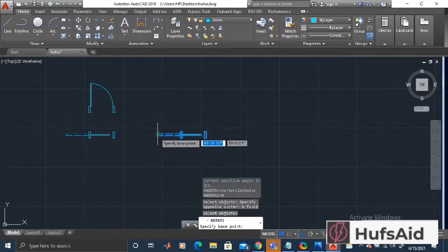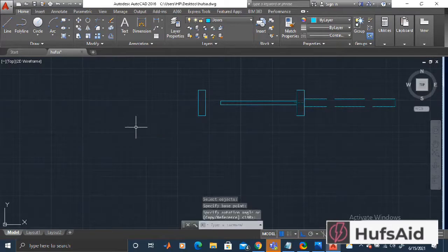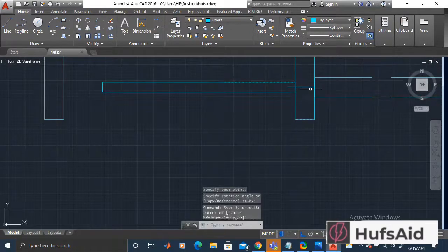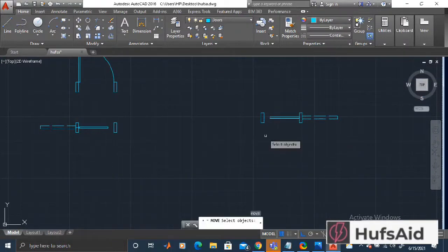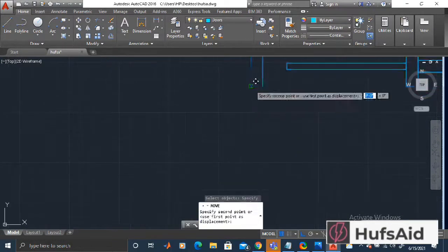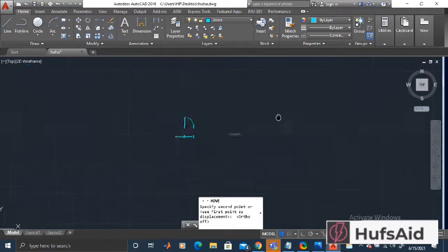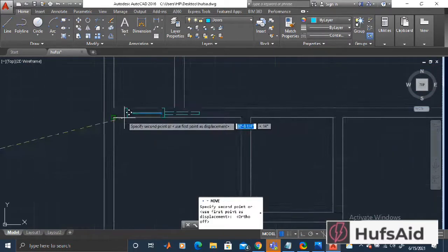And we will have to be very careful while designing our house. With the pocket doors, we cannot have switches around them in their clearance area, or we cannot have any electrical connection or socket, etc., where there is their clearing area.